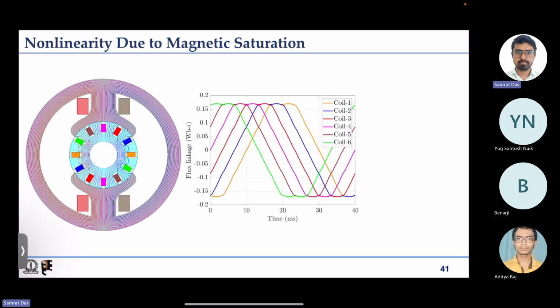So this is a cross sectional view of a DC machine. This is the field winding. Say this is dot, this is cross, again this is dot, this is cross. Because of this kind of field excitation in space, there will be some B distribution, some flux lines, and those flux lines will be coming out and linking the rotor winding. So there will be some B distribution in the air gap.